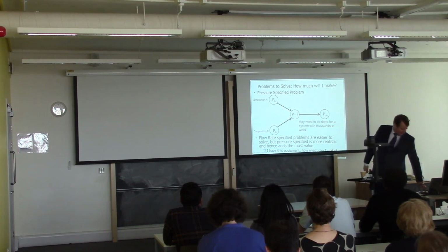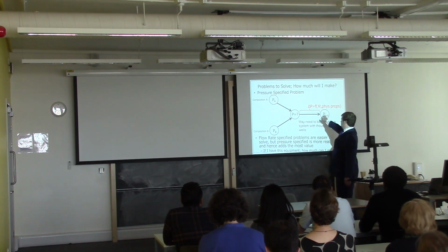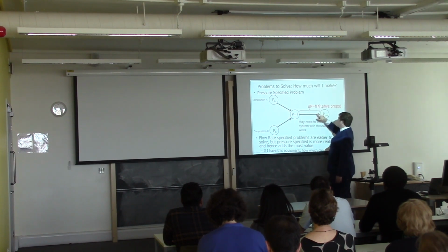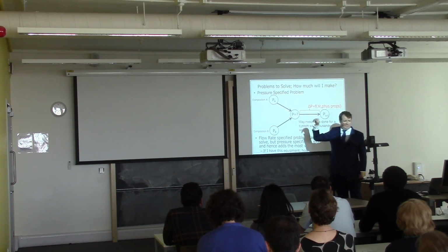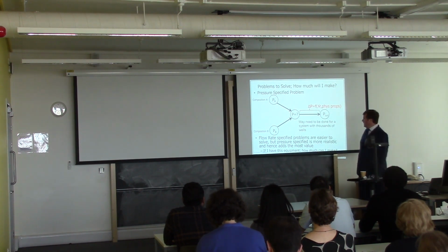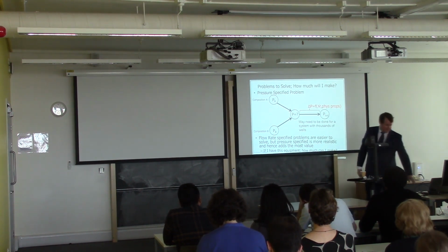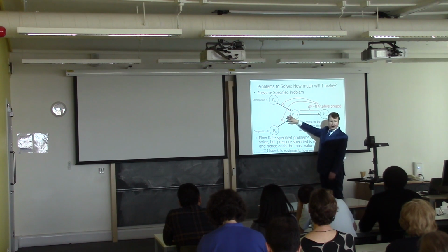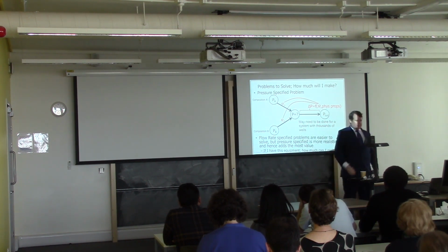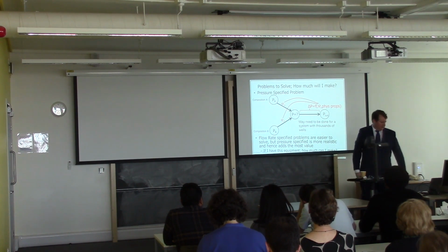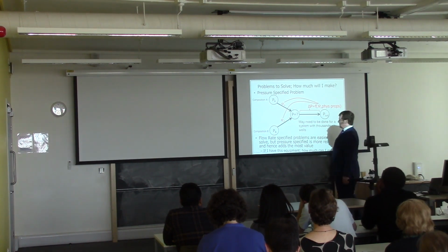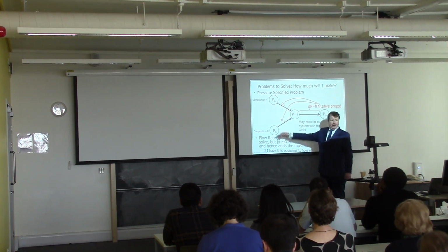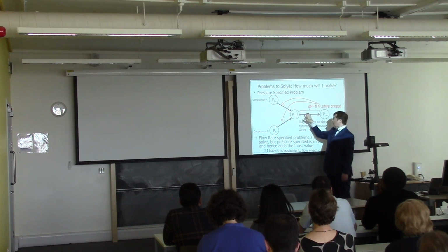So to back calculate that pressure, of course, I know this pressure here, I know the outlet pressure. To back calculate that pressure, for example, I need to know what the flow rate is and the physical properties of all the different phases, etc. But to get that, of course, I need to know what the flow rates are. Those are a function of that. So it's an implicit system. I need to calculate the flow rates and the pressures at the same time. It's well posed, but it's just implicit. There is an easier system to model, which is if it was flow rate specified. If somebody told me there were 5,000 barrels a day from here and 10,000 barrels a day from there, and I knew what the composition was, then it's simple maths to work out what the composition of this is.